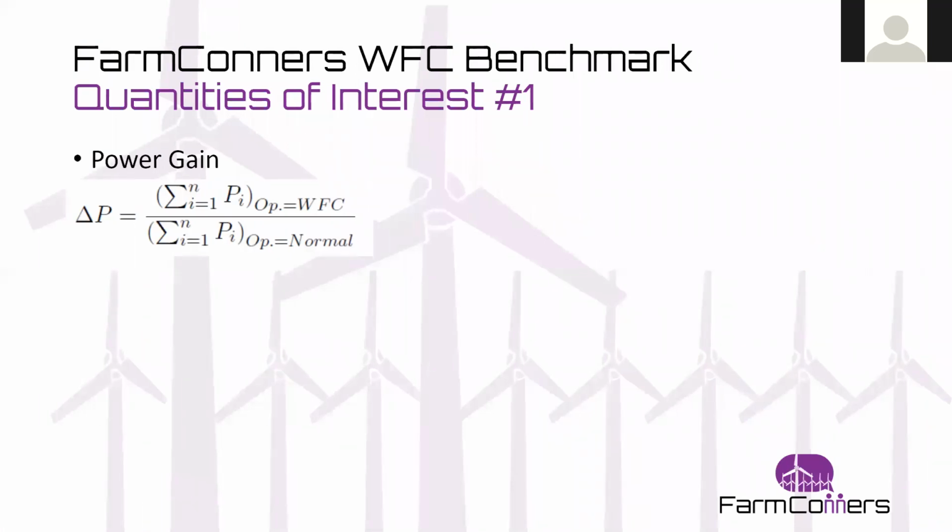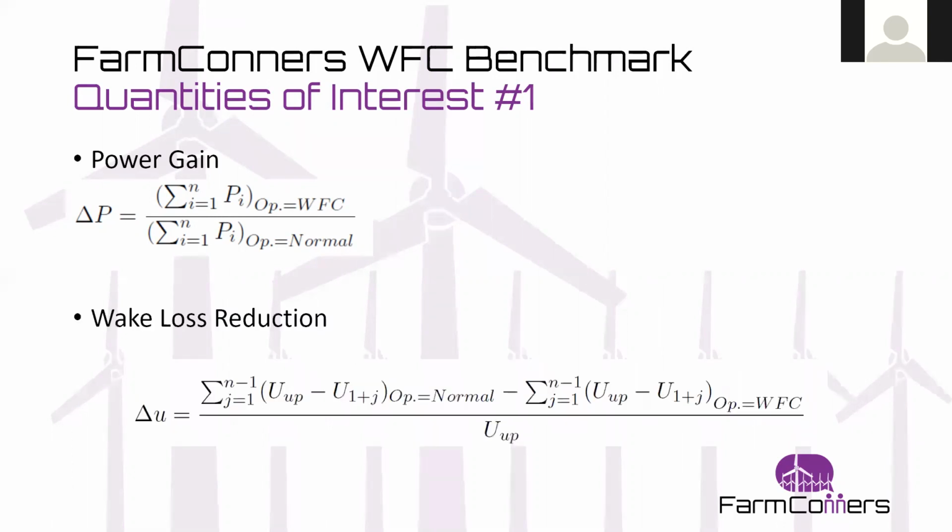The first output feature we will be looking at is the power gain under wind farm controlled operations at the wind farm scale. We will have the power produced by each and every turbine under wind farm control operation, normalized by the normal operation conditions. We have also introduced wake loss reduction as an attempt to avoid potential errors originating from conversion of wind speed to power. Here, U can be either the hub height or the rotor effective wind speed, which is the spatial average wind speed over the rotor, depending on the model capability that you're using.